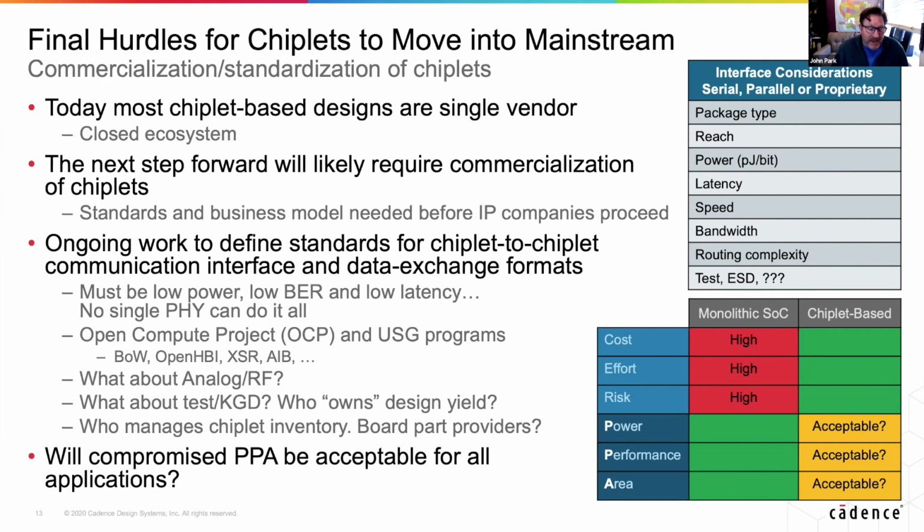You don't know how big the design is going to be. You don't know whether it's going to be 3D stacked. There are lots of factors, shown in the chart on the upper right, that come into play when you start thinking about, okay, I'm going to actually build, fab, and store these chiplets in a warehouse. What do I build it for? Well, I don't know the packaging. I don't know how far it's got to commute. I don't know my power requirements. I don't know bandwidth requirements. There are lots of different things that you don't know. So you end up creating a chiplet that's over designed. That means the IO are too big, it uses too much power, the form factor is bad. So it's a very challenging world.